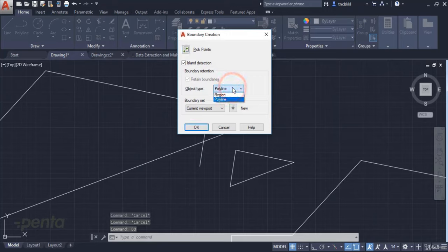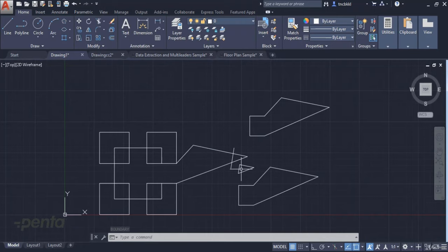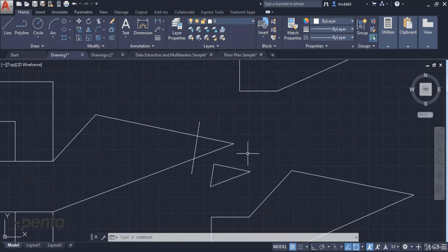We have two methods. One of them is region, the other is polyline. I prefer polyline to create a line. You can also select a plane if you want. So we can use both methods to create an area like this. We can later turn them into a single object with polyline, or we can divide them with the explode command.